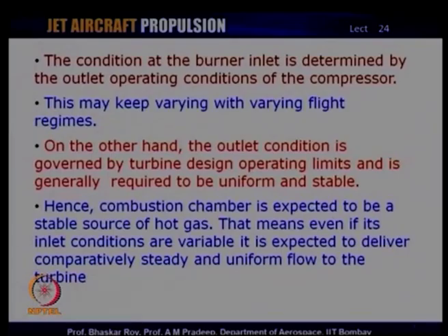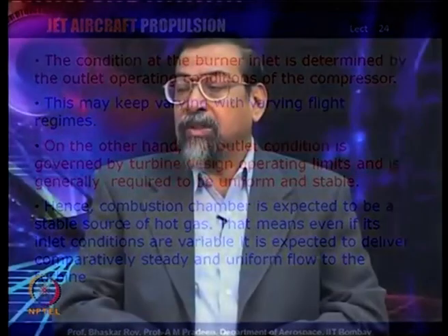On the other hand, the outlet condition of the combustion chamber is necessarily governed by the turbine design operating conditions and is generally required to be uniform and stable. Now, as we have discussed before, the first turbine that faces the combustion chamber is the HP turbine. Now, HP turbine is what faces the high temperature and high pressure gas coming from the combustion chamber.